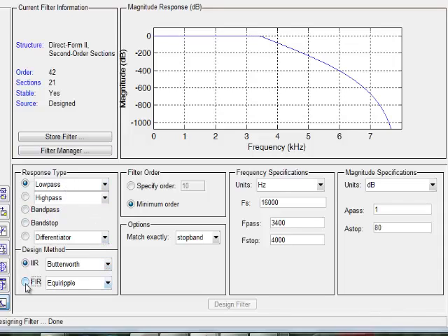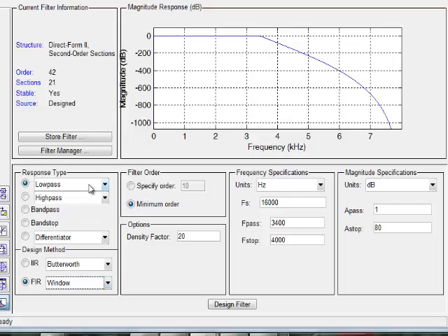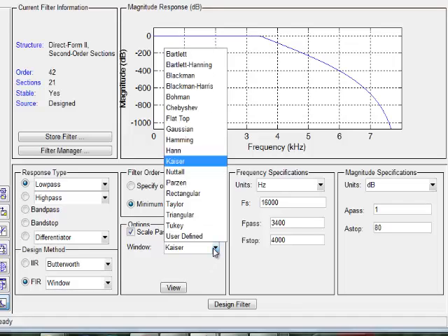Okay, let's have a FIR filter design. For the FIR filter, we can select the windowing method, or we can use the other methods that we already had. So, for example, we use the windowing method, the one that I just explained in the final slides. You can take the window to be anything. So we can have the Kaiser window, or the rectangular window, the Bartlett window, which is the triangular window, Hamming or Hanning.